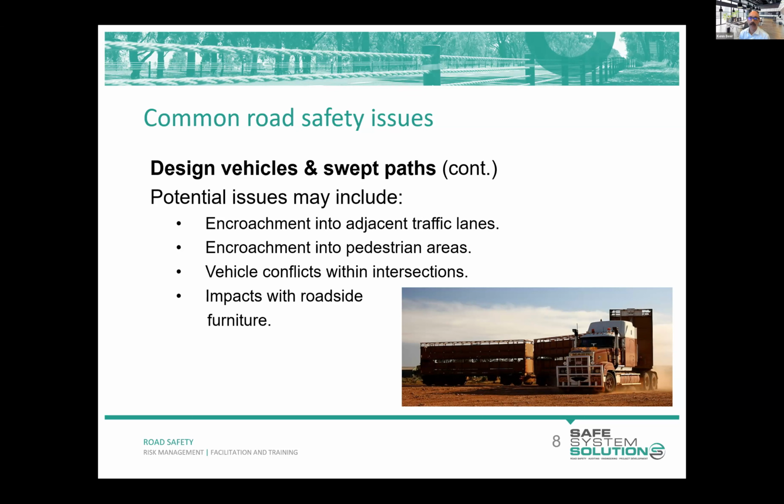Okay. So Tom's just popped in there also. Do we always have to cater for the checking vehicle, e.g. mountable traffic islands needed if the design vehicle doesn't mount, but the checking vehicle does? Well, yes, we do need to cater to the checking vehicle in some way.